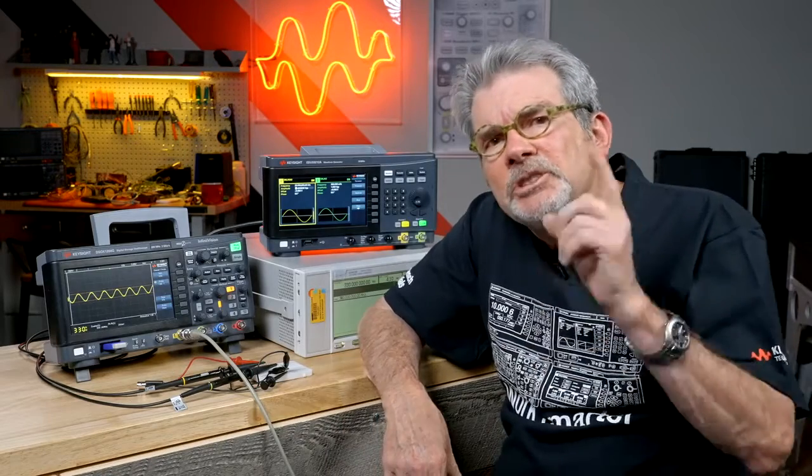So anyway, how much bandwidth is needed? Well, it really depends on two things. What is the maximum frequency content of your signals and how much money do you have? The higher bandwidth scope, the higher it's going to cost. 200 megahertz bandwidth is sufficient for most university teaching labs. In fact, in many university labs I've been in, many of them use 50 megahertz bandwidth scopes. But once you get into industry, higher bandwidth may be required.